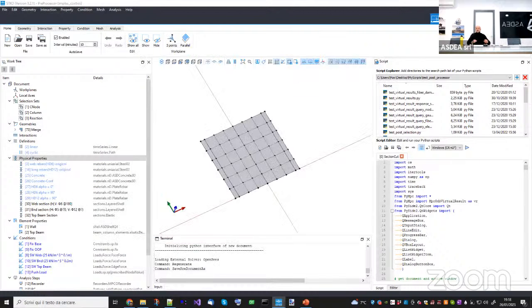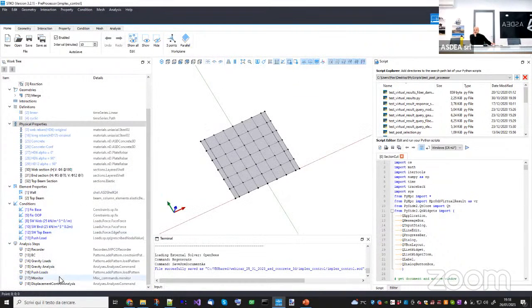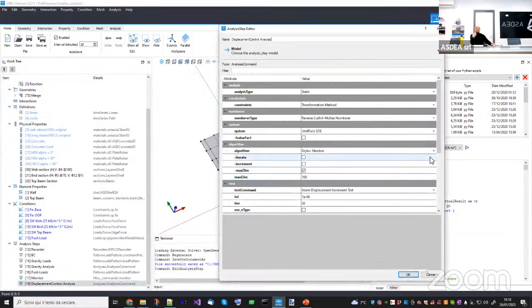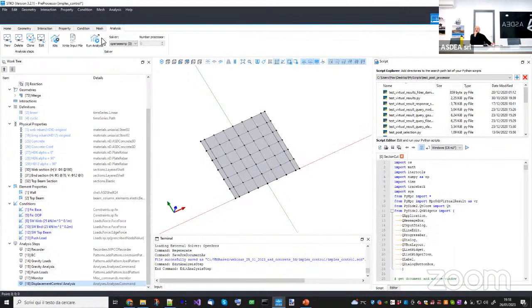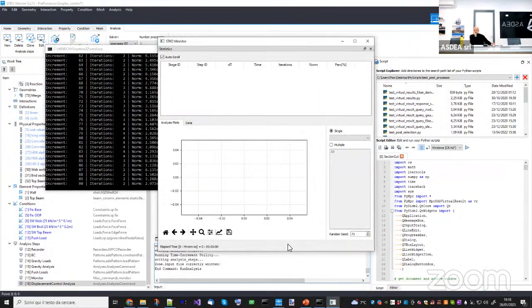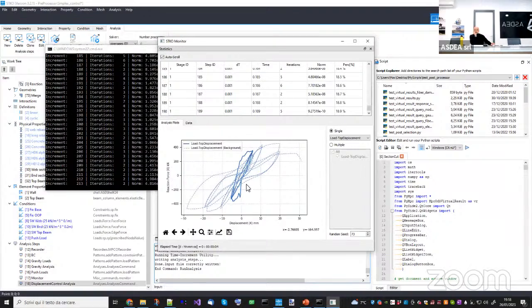Now let's imagine that I know what kind of time step to use for this IMPL-EX algorithm, but let's imagine I start with a very coarse time step like this, and I'm using the IMPL-EX algorithm. I can see errors, something like this. You see, the model will converge, but you will have some instabilities due to the IMPL-EX algorithm.